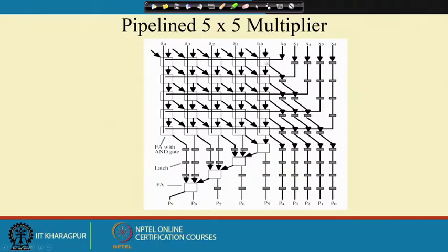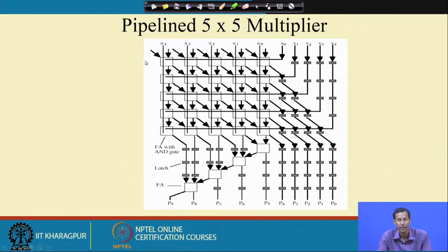The multiplier bits are applied in the horizontal direction. Now, this x0 will first be ANDed in the first row, with no delay element. Next, x1 will be delayed by 1 register. Okay. So then again that will come.